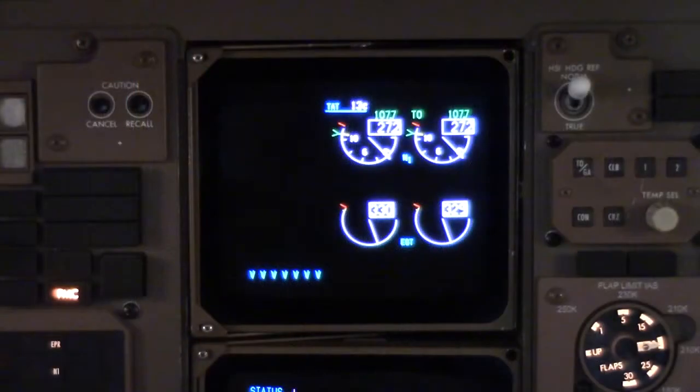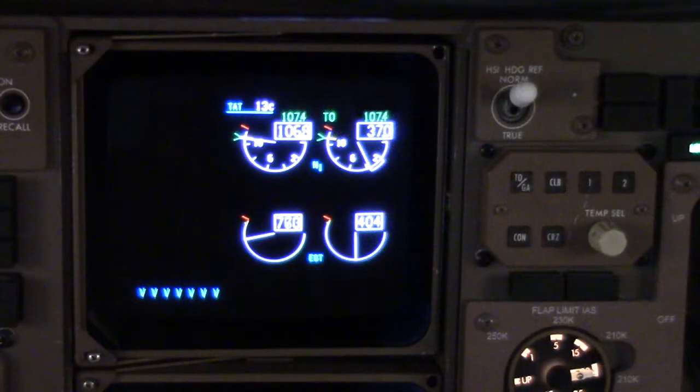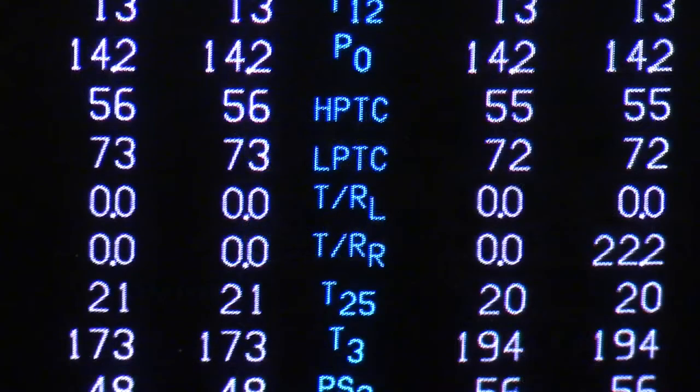Here's what happens. If one of those 4 RVDTs that we're talking about is out of rig, the engines start normally. There's no warning or any messages in the cockpit that anything's out of rig that's obvious to the flight crew. So they go ahead, start the engines, head down, get ready to take off, and then this happens. The left engine's making full power. The right engine, the EEC thinks the thrust reverser is partially open. It will not allow the engine to make full power. It doesn't want to destroy itself.